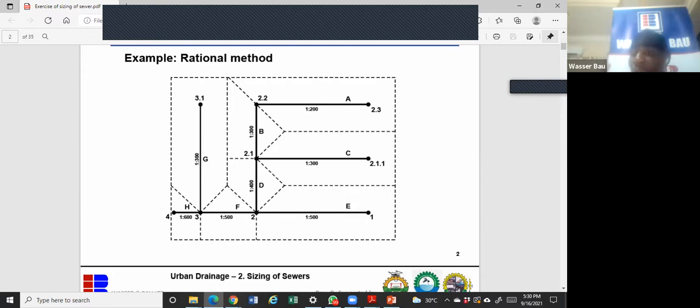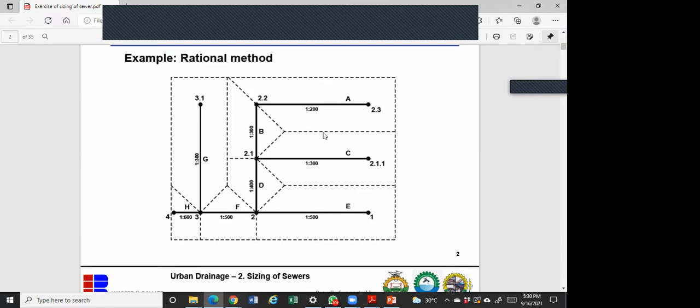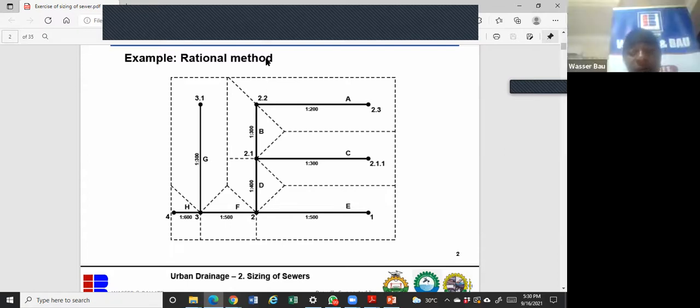As in, before it gets to the drain, I don't mean on the inside, while it's inside the drain. Before it gets into the drain, for it to flow for long. Sorry? Did you say 100 hectares? Yeah, that's the limit for using this method. It's not advisable for a land size that's more than 100 hectares for you to use the rational method.